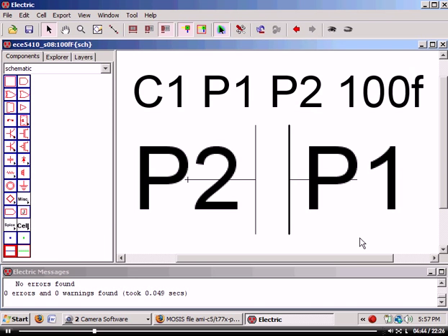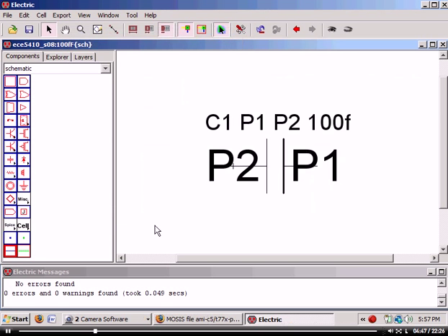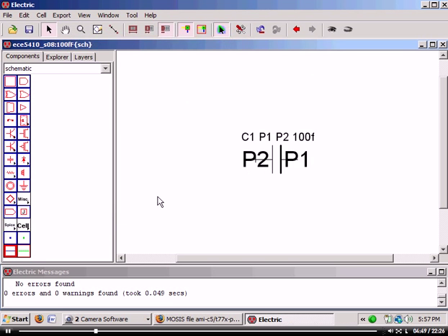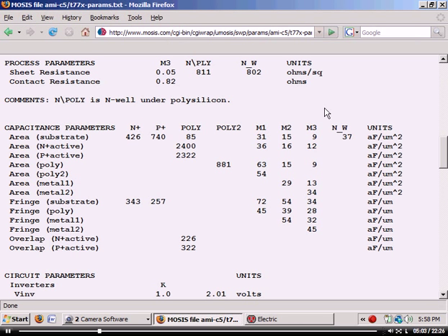Oops. Before I do the layout, which is the whole thing, I said there was a big parasitic capacitance from poly1 to substrate. Right? Now, I can add that capacitance in the symbol in many ways, but before I go back, let's see how big that capacitance is. So from poly 2 to poly 1 is 880 attofarads. From poly to substrate is 85, so it's about 10% of the size. So should I waste a lot of mental energy in trying to get an exact value here? No. Okay, so I'm going to put 10%.